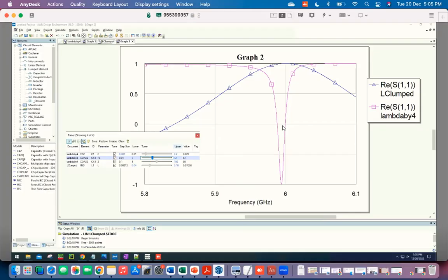So ideally speaking, any such connections should not have any significant capacitance or inductance because you're trying to maintain the 50 ohm nature of that. This capacitance usually will be designed on the chip itself. So if you're making a transmission line, you will make it of the right length and right next to it will be the capacitance. In fact, it is nothing but just a gap in the transmission line.